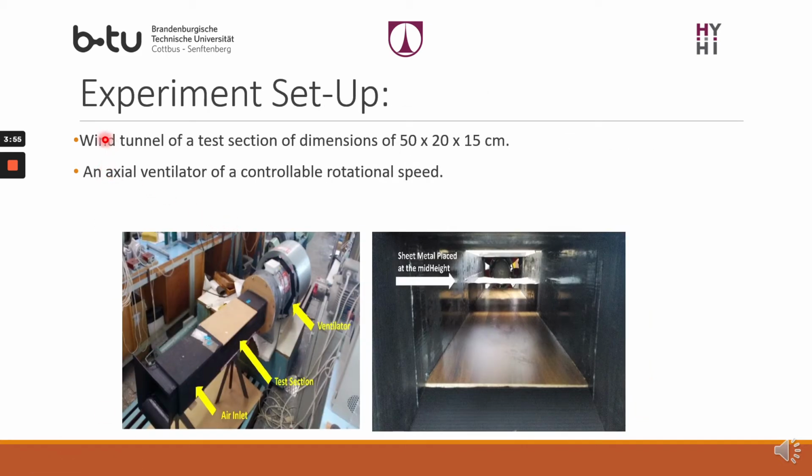The experiment has used a wind tunnel. The wind tunnel had a test section of 50 centimeters in length, 20 centimeters in width and 15 centimeters in height, connected to an axial ventilator of a controllable rotational speed. The test section had the metal sheets placed at exactly the mid height of the section.